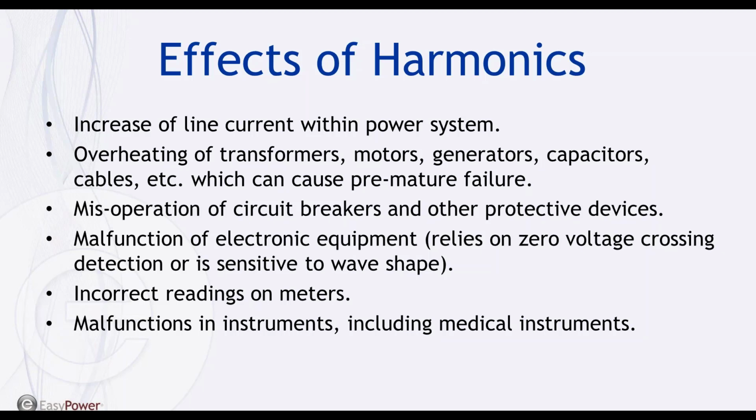Harmonics can also cause misoperation of circuit breakers and other types of protective devices, as well as malfunction of electronic equipment. Harmonics can also result in incorrect readings on meters, which can cause a whole set of other problems, and can also cause malfunction in instruments, including medical instruments, which can obviously have serious consequences.